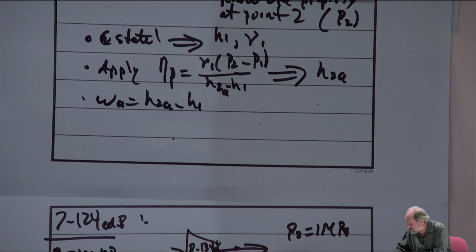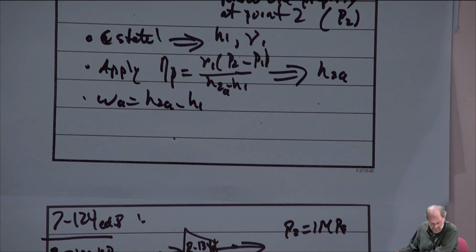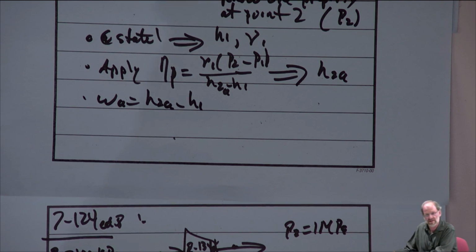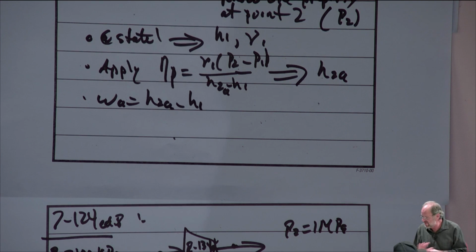We're given the isentropic efficiency of the compressor as 87% or 0.87, and we want to find the exit temperature, T2. And I should really put T2 actual now, right? They ask for the exit temperature. The author rarely uses the word actual exit temperature, but we just know that there's really only one exit temperature, right? It's 2A. 2S doesn't exist. It's a tool we use. So if it asks for the exit temperature, it's asking for the actual exit temperature, not what the temperature would be if it were an ideal compressor. That's not what the author asked. Anyway, it wants us to find the power input.